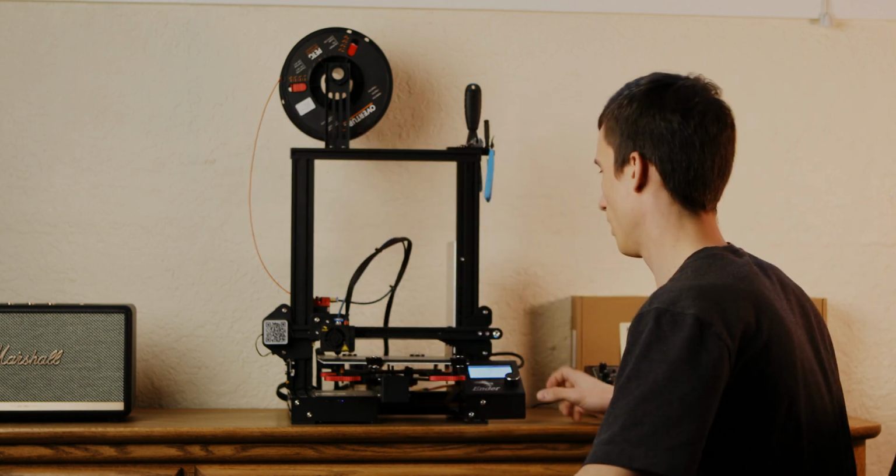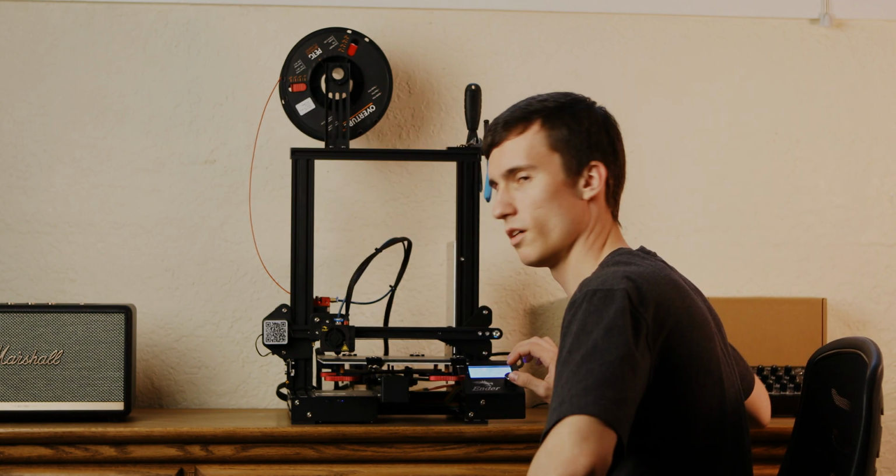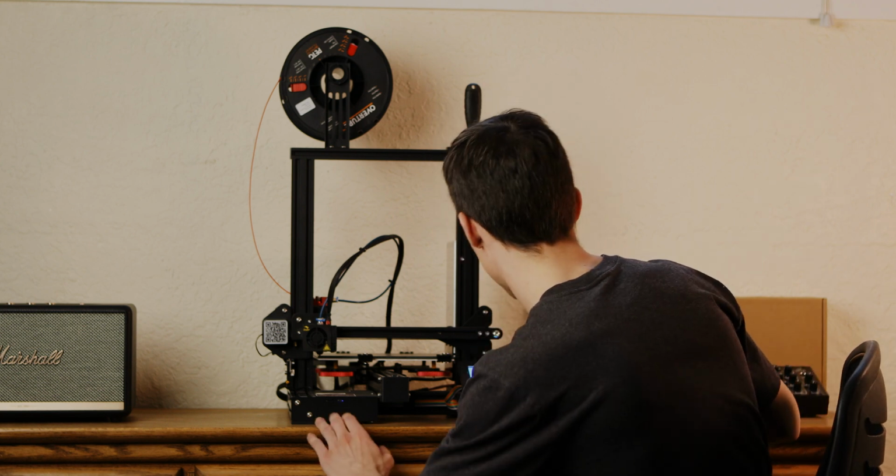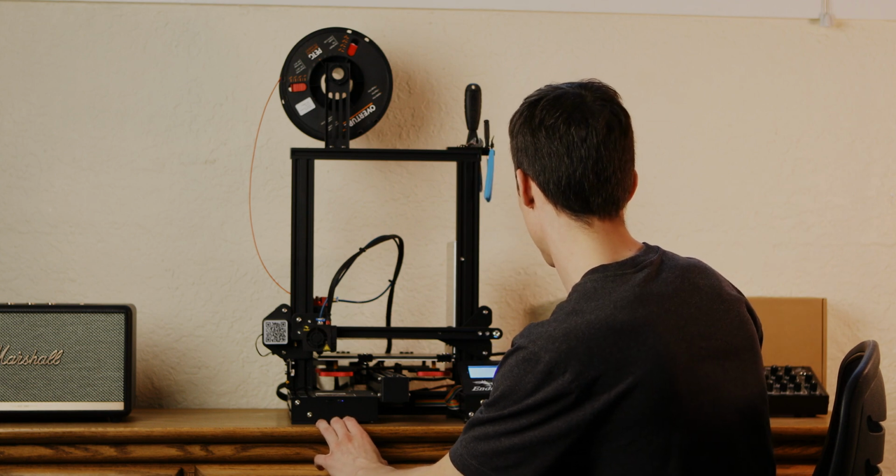Alright, now I'm going to home the printer one more time, and that's pretty much the point where I'll be able to start printing. So the last step before we get started printing is we have to clean the bed, and that improves adhesion and will increase your success rate. You could do 2 prints back to back and not have an issue, but you never know. You want to take the safe route rather than risking it, unless it's small prints. Alright, I'm gonna go ahead and disable the steppers